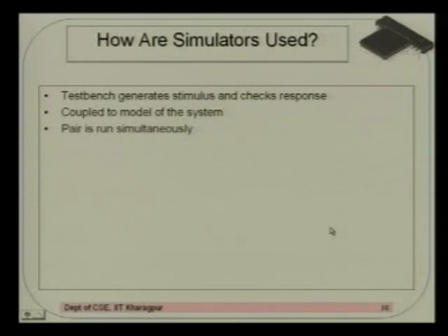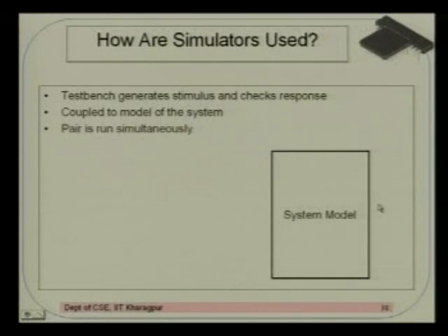So I would come to how simulators are used. The first thing that you have done right now, or rather seen some glimpses into, is that you have got a system model, a description, which you have described using a piece of Verilog constructs. Now this particular model is supposed to be what I call a synthesizable piece of Verilog code. That means all the constructs which you write, all the language features that you use, have got hardware connotation. For example, always can be synthesized, but initial block is not synthesizable.